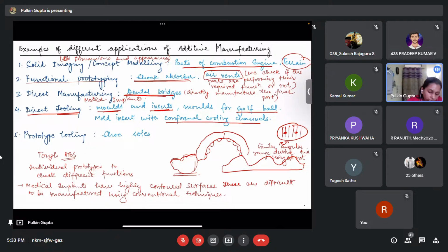Now, one of the types is prototype tooling. As the name suggests, it is for prototyping. When very quick changes are made to the molds, in such a case we could make molds of materials that would sustain a little less than stronger molds, since there are changes to the molds very fast.